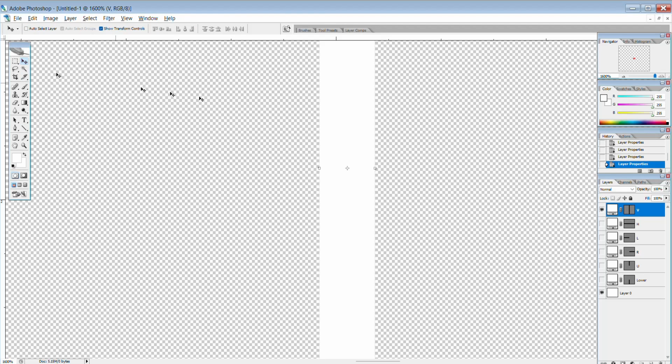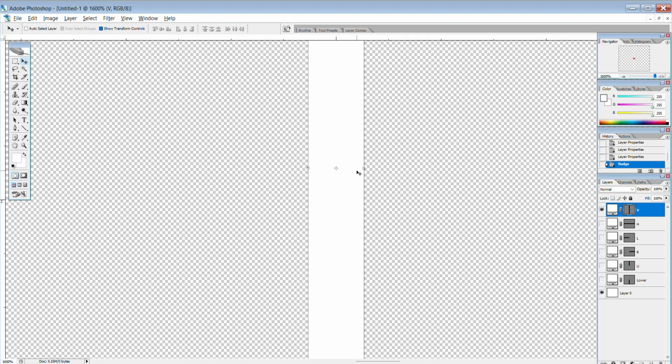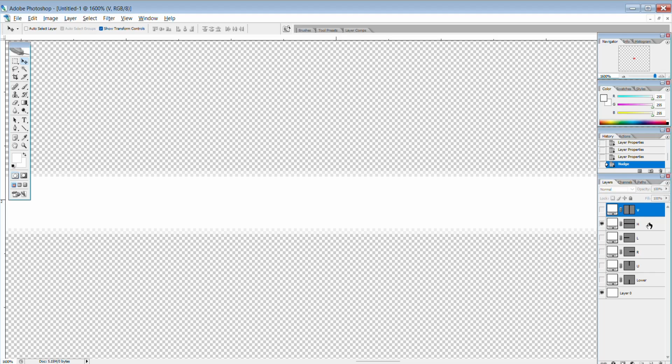I'm now going to click on the Move feature, and if you click in the actual box, you will notice that it has drawn a black line around it. If I unclick, you'll see the black line goes away. If I click, the black line reappears. Now, by using the Control and the arrow keys, I'm able to move this over to try and get this center point, which represents the 2.5-inch mark, as completely aligned between these two as possible, and you'll see that that is now perfectly aligned.